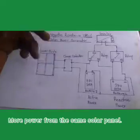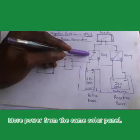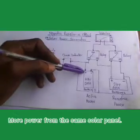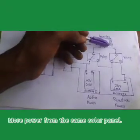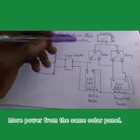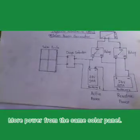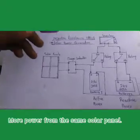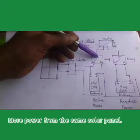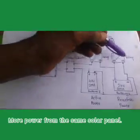Then when you want to consume this energy, instead of running it the conventional way, which is connecting the positive of the inverter to the battery positive, and the negative of the inverter to the negative terminal of this battery, now watch, we have two relays that are involved in this. The common, normally closed, common, normally closed, normally open, normally open.